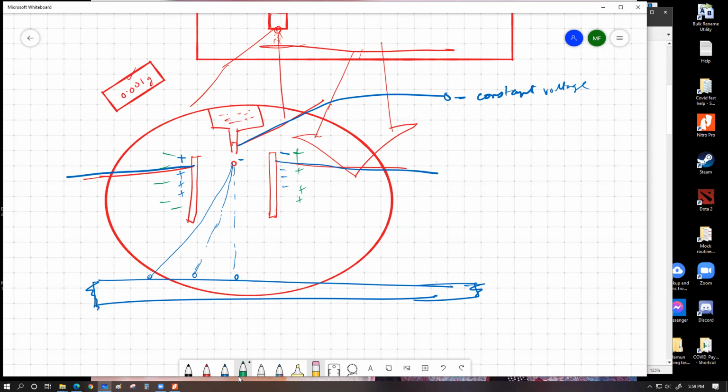So I'm trying to use a different color to give you an idea that this happens individually and differently at different time frames. If we charge it oppositely, then it's possible that we can bend the ink droplet in the opposite direction, so it's going to fall onto a certain location. It's important to understand that exactly where this ink droplet drops depends on multiple factors. Number one, the weight of this drop, which tells us how much time it takes to fall from the output level of the nozzle to the paper level, because it's going to fall due to gravity.